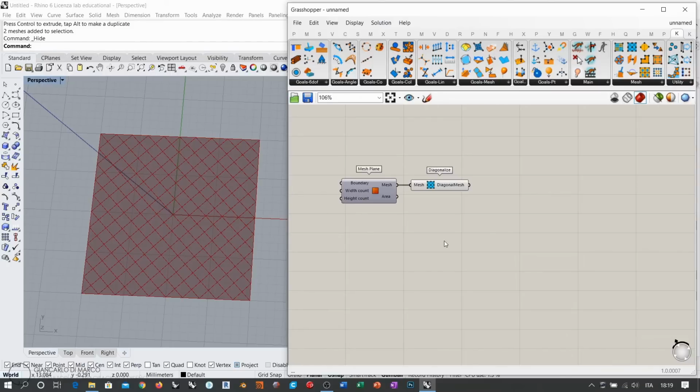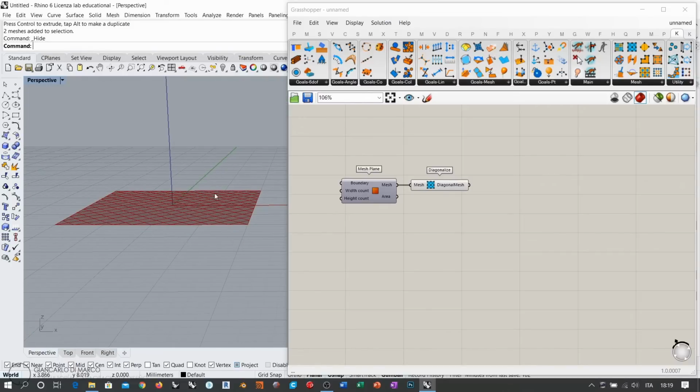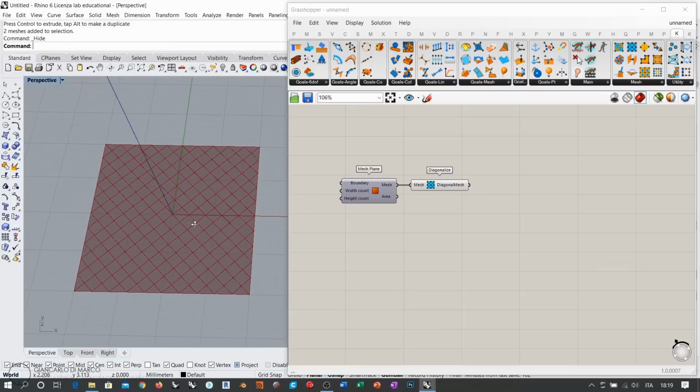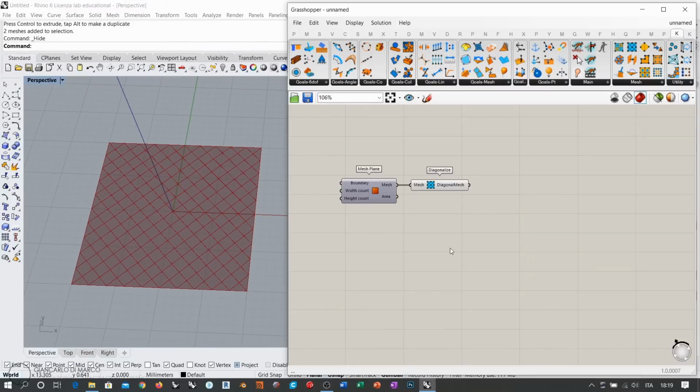This is something that is not so common as well, because if you think about an inflatable structure, it's very difficult to differentiate the value of pressure in two different areas of the same body. Unless you have some isolated chambers here where you can apply two different pressure values, then it's impossible physically, right? So the more common approach to this is basically, instead of affecting pressure, so pressure is going to be one and constant, or well, parametrically variable, but one single value. Okay, you differentiate the properties of the material in order to produce a differentiated behavior. So how can we do this?